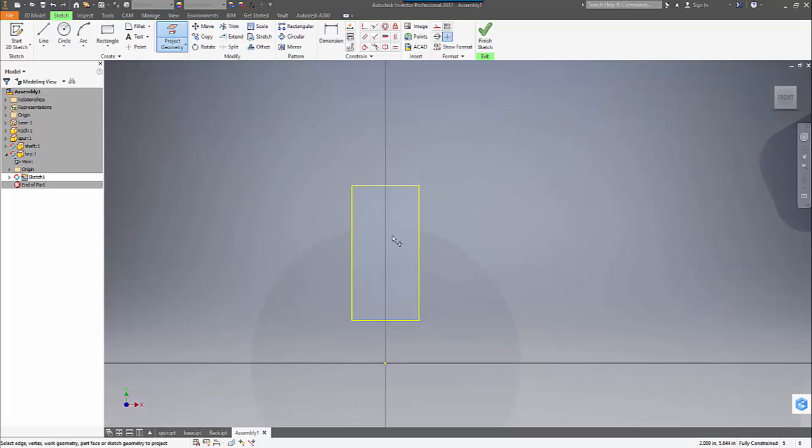The deal is, though, when we constrain all this, this needs to be totally at top dead center to be accurate for constraint purposes. And we know it'll constrain because we created the geometry from the original spur gear information. If we create the key slightly smaller, which typically is the case because you want a sliding fit with the key, the problem is constraining that slightly smaller key.